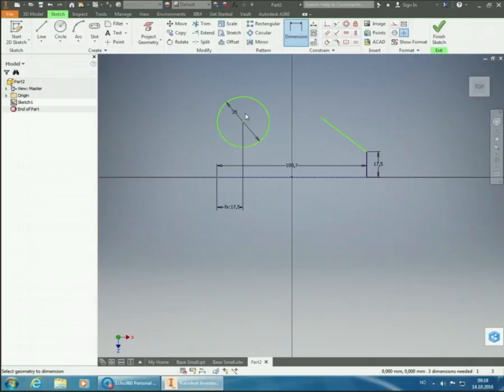But if I now change, you guys don't need to do this, but if I change the diameter of my circle now to 40, then this one should become 20. So I go in here and I put in 40, and suddenly I have 20 down here, because now it's doing half of 40 instead. So it's a good way of building in automation in your parts.